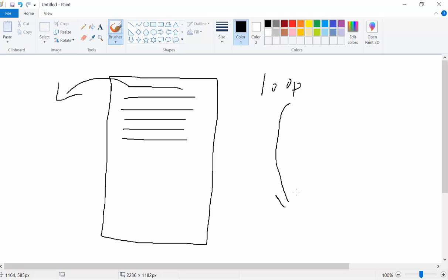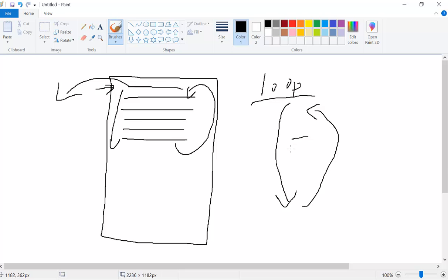After it's done with all the lines in the loop, it's going to come back because there's an instruction pointer. It's going to point to each line sequentially. So after all the instructions are executed, it is able to come back to the top and rerun it. So you need a loop. Usually when you're running a microcontroller, you use a loop to keep that thing running. But definitely you have if statements to make judgments on the signal sensed from the sensor. But this is how that microcontroller works. So the FPGA program is different.